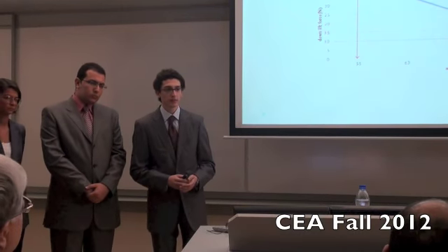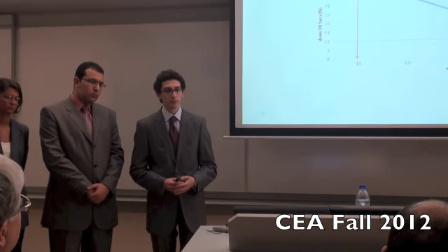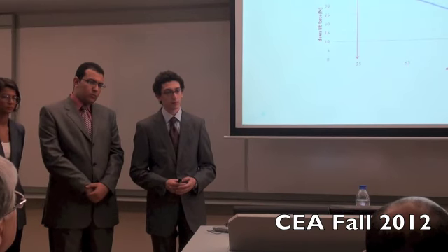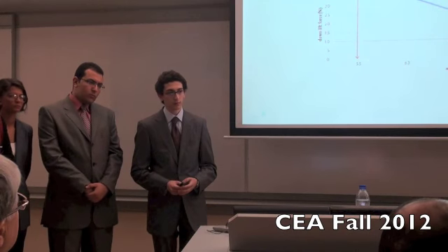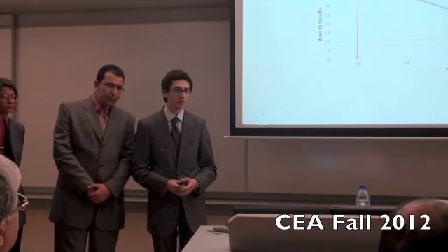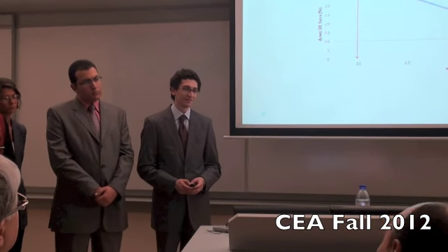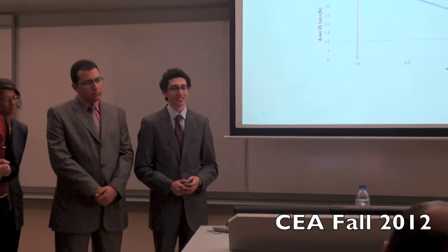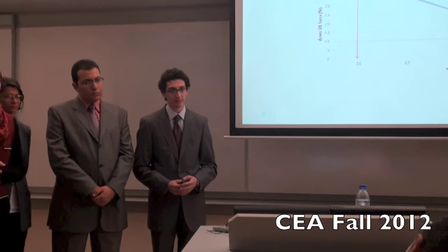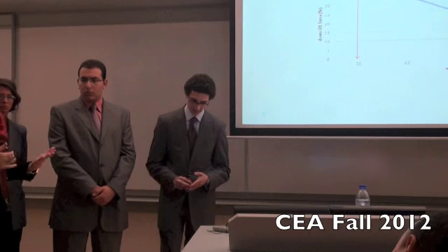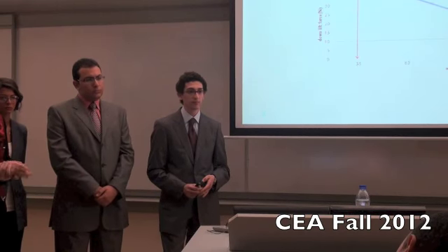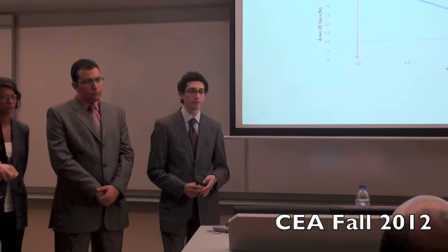I would advise you that you should consider normal wind loads, neglect the 10 miles per hour because this is really unrealistic. You should consider something normal. Otherwise, a load of 3.5 kilogram applied on the whole cross section means that it is negligible. All of this work is not really effective because you are talking about very small numbers. When I increased the wind speed as a client, I got a bit bigger load, but I abided by the speed I have. Now you have to think of larger wind speed because these numbers are not really realistic.